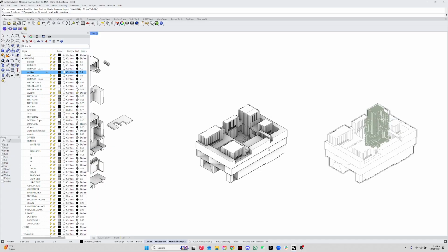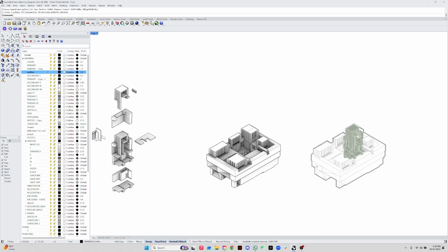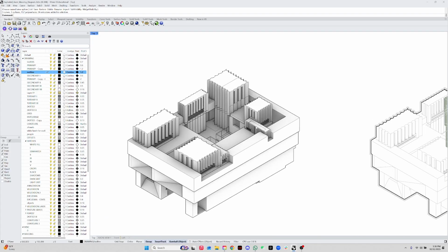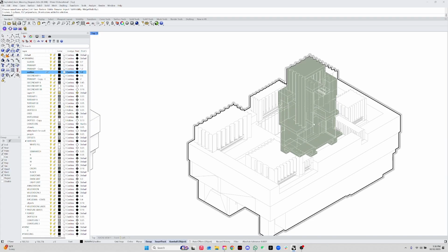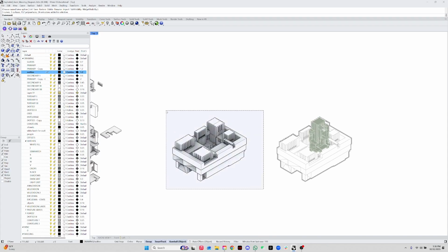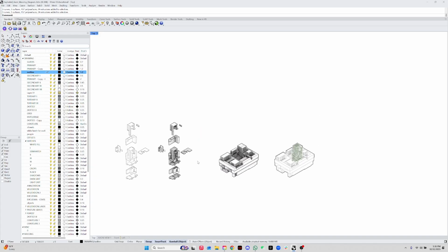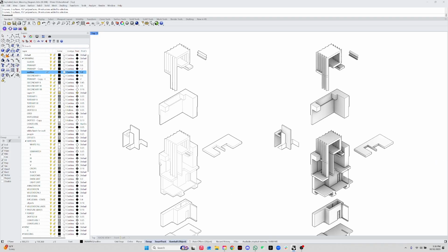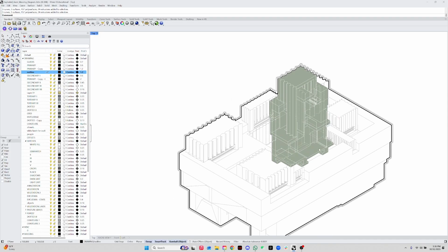The reason why I do that is so that when I'm drawing on the top view, if I'm missing something, I can be drawing hand to hand next to the model. And if I want to do anything here, I can just do a make 2D really quick and change it here. So that's why I do this in terms of modeling and also drawing. The other reason is to do hatches, and that's why I wanted to go over it here. We're not really going to do hatches on this one because this is more of a location diagram, so you don't want it to get too busy.